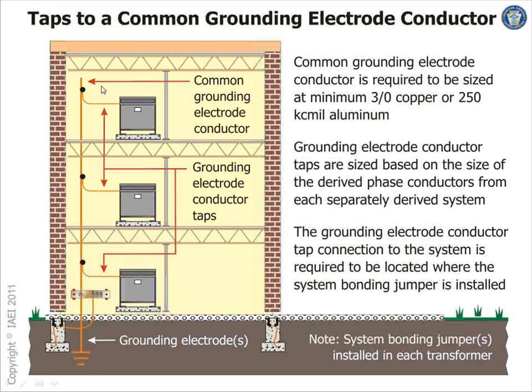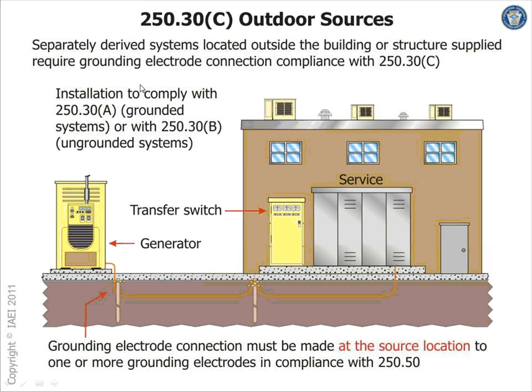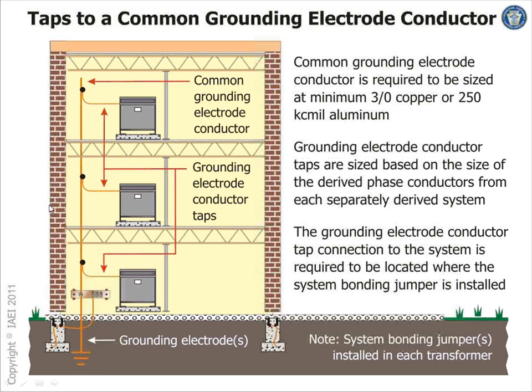Here's what you mentioned. If you have a riser, you can have a grounding electrode system going all the way up, and you tie into it with irreversible means and tie each and every one of your grounding electrodes. Engineers draw this one all the time. If you do it this way, it cannot be less than 3/0 copper or 250 aluminum. That's a riser, grounding riser. This has to be irreversible means, either exothermic welding or crimp. You crimp it, but you can't use split bolt on it.